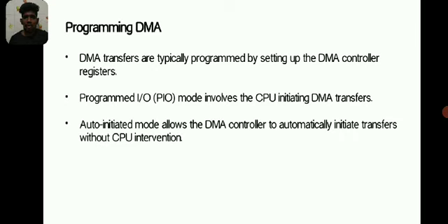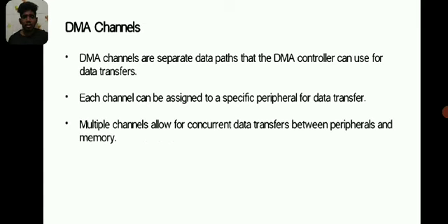Programming in DMA. DMA transfers are typically programmed by setting up the DMA controller registers. Programmed input output (PIO) mode involves the CPU initiating DMA transfers. Auto initiated mode allows the DMA controller to automatically initiate transfers without CPU intervention.